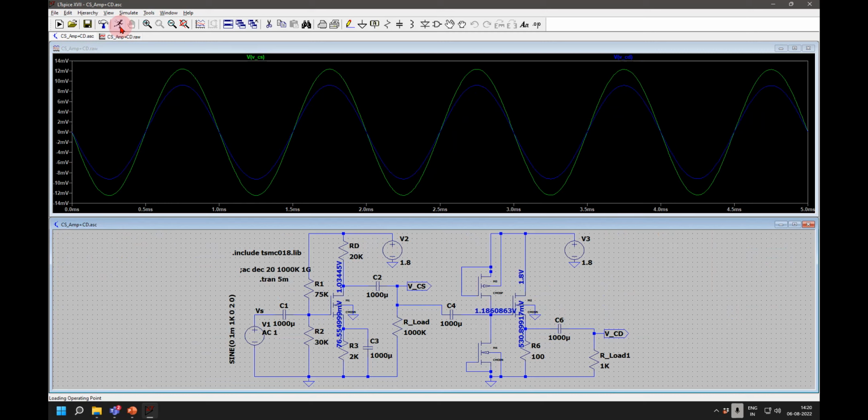Here we are using MOSFET for biasing. The bottom NMOS is off. Top is also off. Yes, so it will provide very high impedance. Correct. And changing the W, increasing the width, will not change the impedance, right? No, relative to the PMOS, both are off only. Why does increasing W increase this R out? I mean, R out is 1 by lambda ID, and ID is 0 here, right? It is off, cut off.